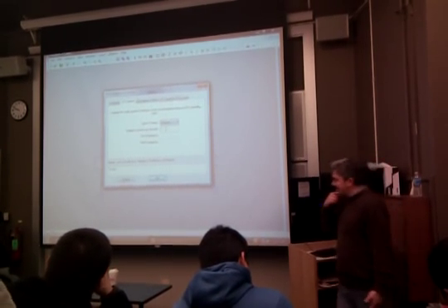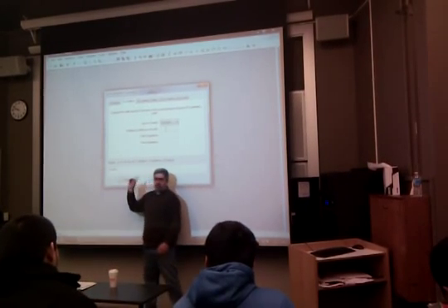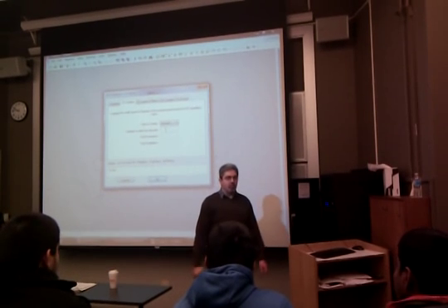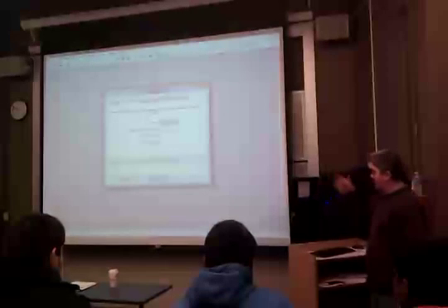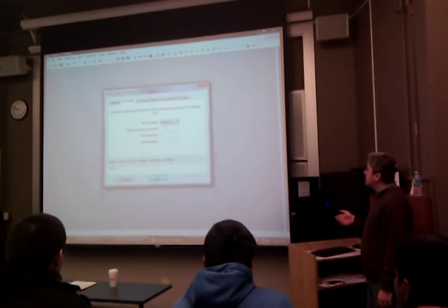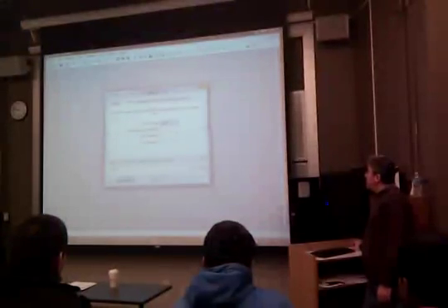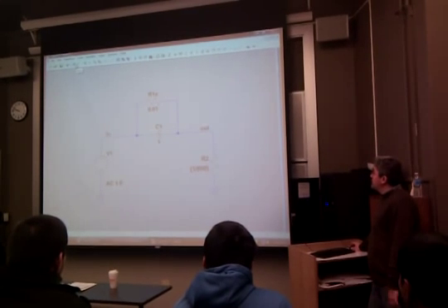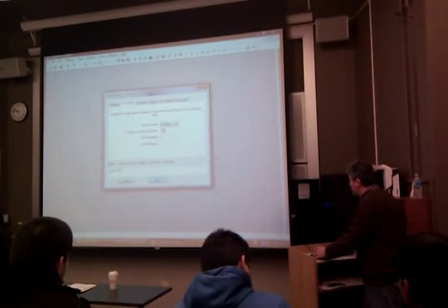By the way, as I'm filling these out, we're entering in a line of Spice code here. If you know how to enter the Spice code, you don't have to do this. I normally don't do this, but I'm just kind of showing you where it's at. Number of points per decade, okay? How did I get this? Oh, when I hit the simulate button, there was no simulation command. So it's asking me. So, decade, number of points per decade, maybe 100 points per decade, start frequency, in hertz